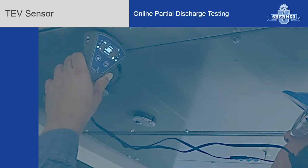electromagnetic waves can easily be produced by external devices such as fluorescent lighting systems, LEDs, battery chargers, heaters mounted to the side walls, etc. So many times we'll use a TEV signal, but then we'll also use the UHF or the high frequency CT or even the ultrasonic airborne sensors as backup techniques to say, yes, what we're hunting here is in fact actual real partial discharge, whether it's surface tracking, floating discharge, or corona.